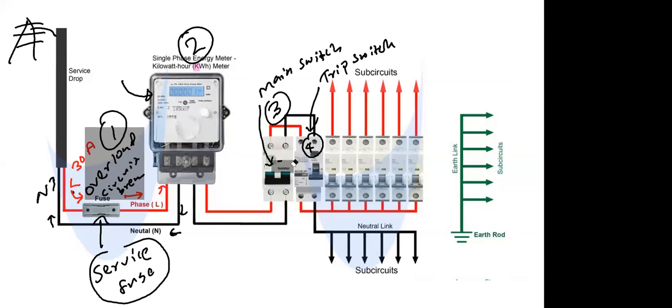But sometimes when someone gets electrocuted, whenever there's a leakage of electricity from your house, from the main circuit, the trip goes off. But in some houses the trip is not working. Then what happens? The person will die, because the leakage current can continuously pass to the consumer, to the earth, to the ground. Then you get electrocuted definitely and will die. If you observe someone getting electrocuted, don't pull that person, don't touch. First thing you should do, you have to disconnect the supply from the main switch.